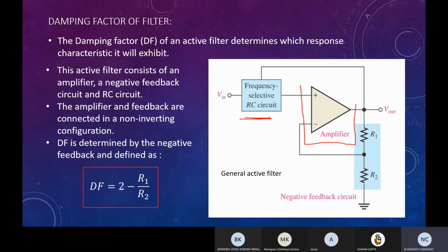So why do we use an amplifier or an op amp? This op amp is used to get our desired gain instead of just a gain less than 1. With this op amp, we will get a gain that is greater than 1, or any gain that is our desirable gain. This op amp is connected in a non-inverting manner. You should have studied this in the second workshop.